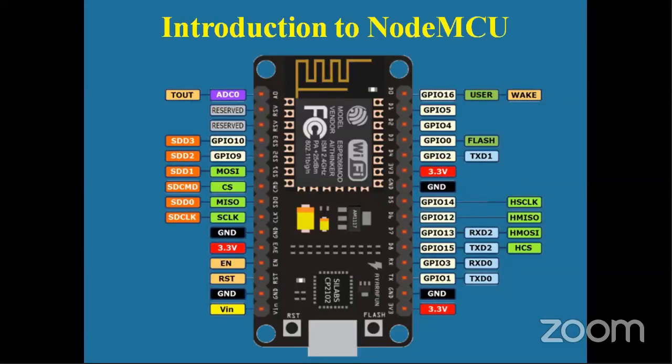You do the connections in the same way, you write the programs in the same way, and you use the same functions: pinMode, digitalWrite, digitalRead, delay. In fact, you use the same Arduino IDE to write your programs for the NodeMCU also.